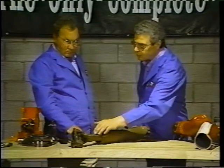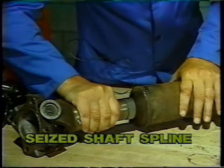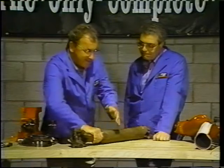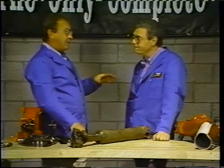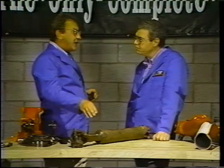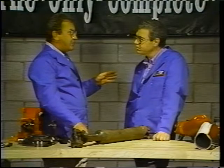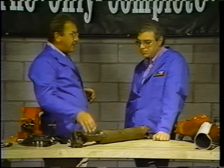Now, here's a slip spline example. What happened to it? Well, what we see here is a shaft spline that's seized. Improper lube procedures, particularly in the area of lube cycles, lead to this kind of problem. Now, this spline was not glide coated. Spicer's glide coat is a specialized coating that's applied to the tooth shaft spline to help prevent seizures like this.